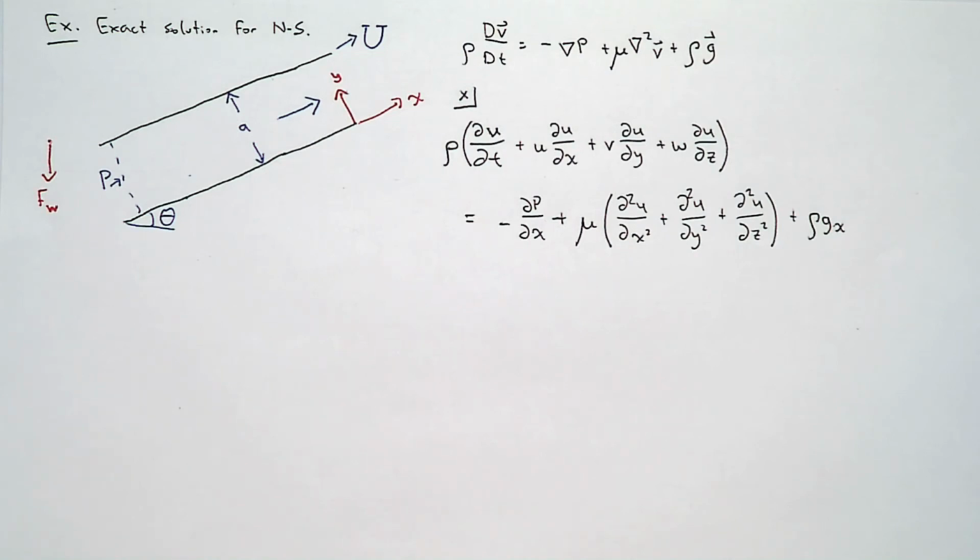So that is the Navier-Stokes equation for this one-dimensional flow that moves in the x direction. And now let's start to simplify this equation. We know that this plate is moving with a constant velocity, so there is no change in the velocity of the plate. We have a constant pressure gradient and a constant acceleration force. Does the velocity change with respect to time, if everything is constant? No. All my forces are constant. There is no change in velocity with respect to time.